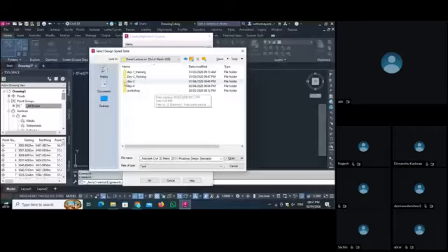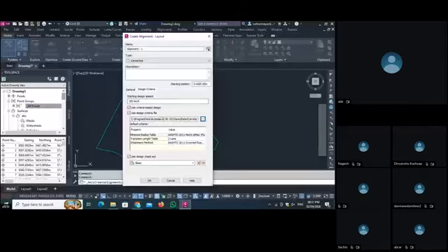You can select your design code set from anywhere in your folder and use it here. But make sure your design code is an XML file. It is mandatory to use an XML file to upload into Civil 3D. So the file type is very important. Every time I draw your attention to this: you must know all the file types wherever required.